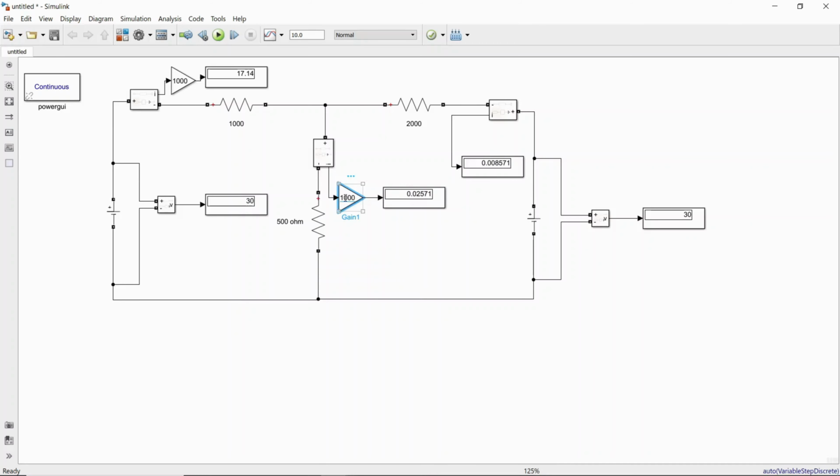And just once again connect the Control C, the gain value, and you can use this connection also. Just delete it, Control V, and just use this button and press Control R. It will rotate and you are going to get the value like this. And here you connect the output.